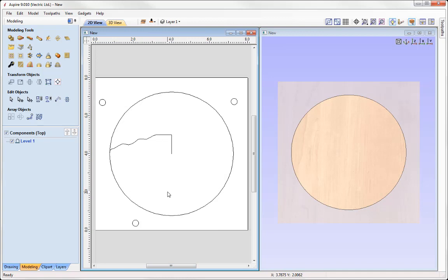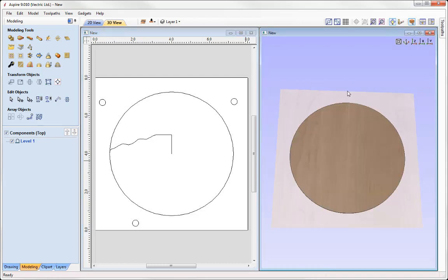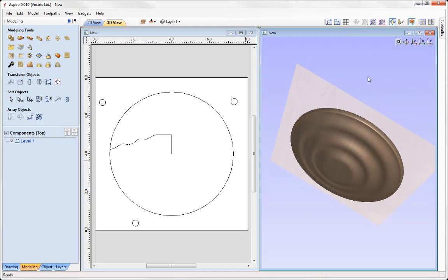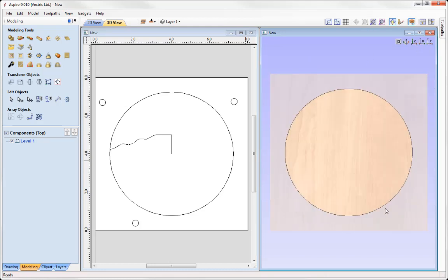Then we're going to switch to the top side here. And now we're ready to alter the cross section so that we can create the recessed shape into the bowl that we already have so far. Okay, let's put that back in Z. And so as we're creating a recessed version of the original cross section, we just need to tweak it a little to make it a little smaller in height.